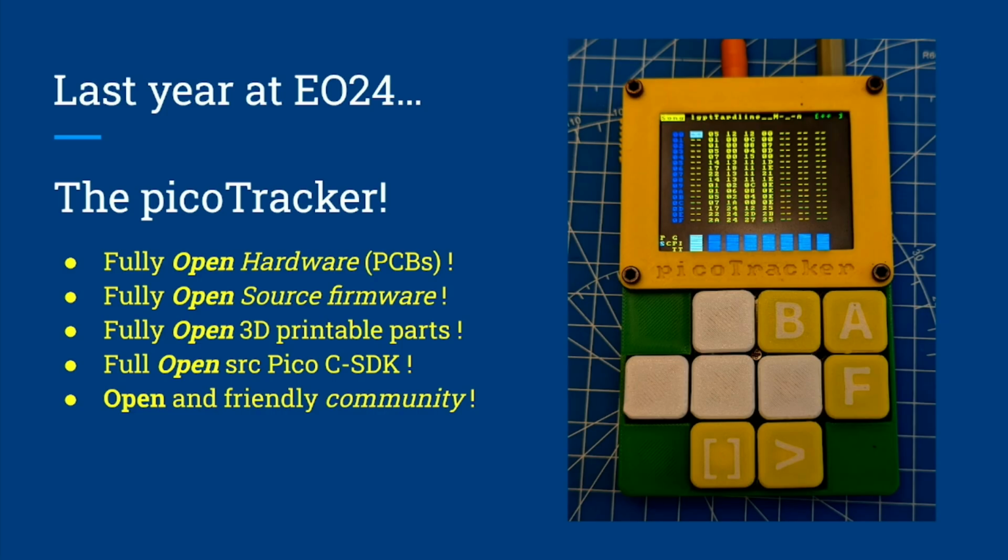And by this stage also, you can see this is not the same unit I just showed you, because Francesco had actually created a portable model, which was a custom PCB that he designed himself, not based on the Pico, but based just on the microcontroller, the RP2040, and a completely custom board with a DAC, optocouplers for the UART that goes out to the MIDI, all the stuff that was basically required, but he just built a custom board versus the crazy wiring together of multiple dev boards that was the first prototype.